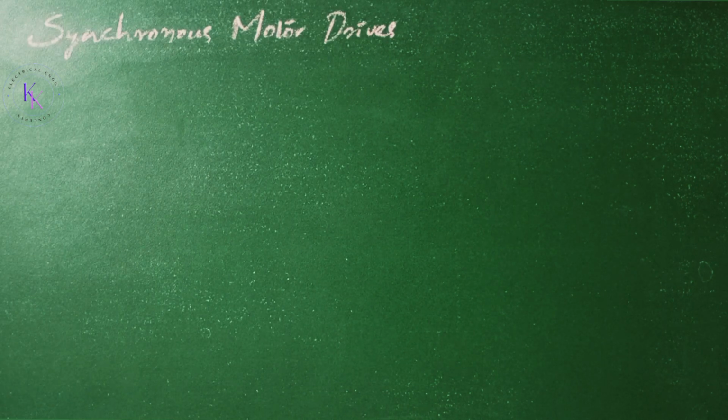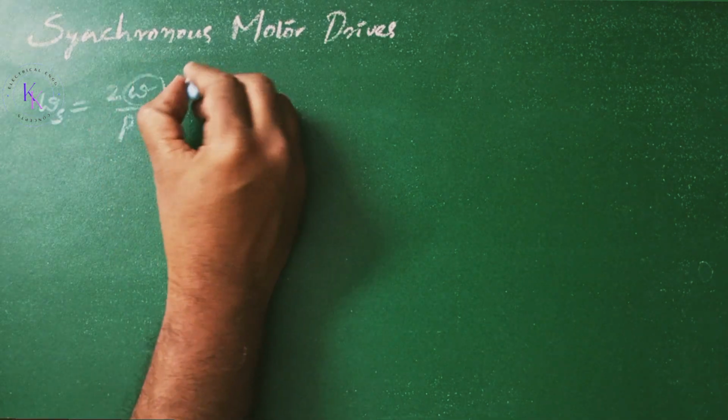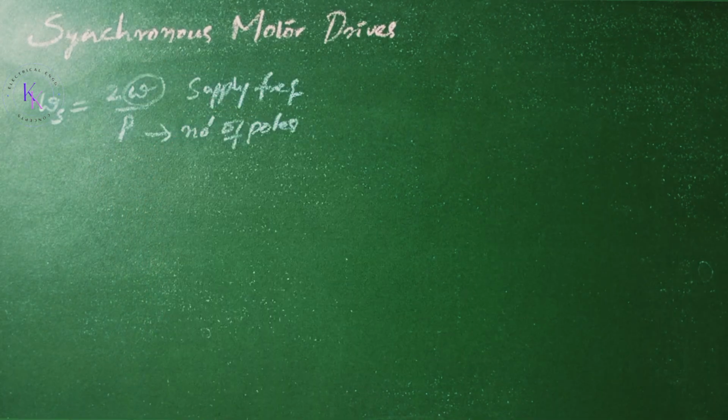A synchronous motor is a constant speed machine and always rotates with zero slip at the synchronous speed, which depends on the frequency and number of poles. A synchronous motor can be operated as a motor or generator. The power factor can be controlled by varying the field current. The cycloconverters and inverters are widening the applications of synchronous motors in variable speed drives.